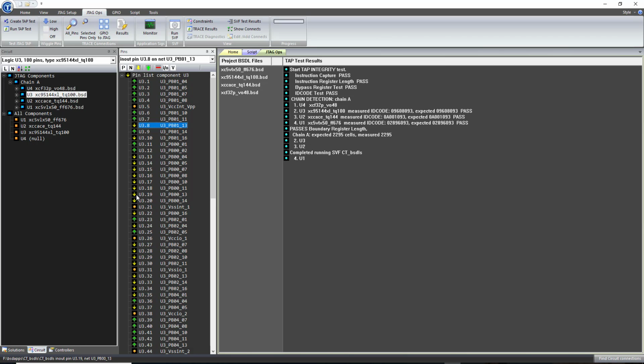All of the pins are tested when one pin is driven, and the values on those pins are captured at the TDO scan point. So if we want, we can look at the I/O type of a pin. It's an input-output. It could be just an input or an output, for example, an O or a B for a buffer. So if we wanted to pick a pin to wiggle or do some other operation, we might want to know what kind of I/O pin it is.